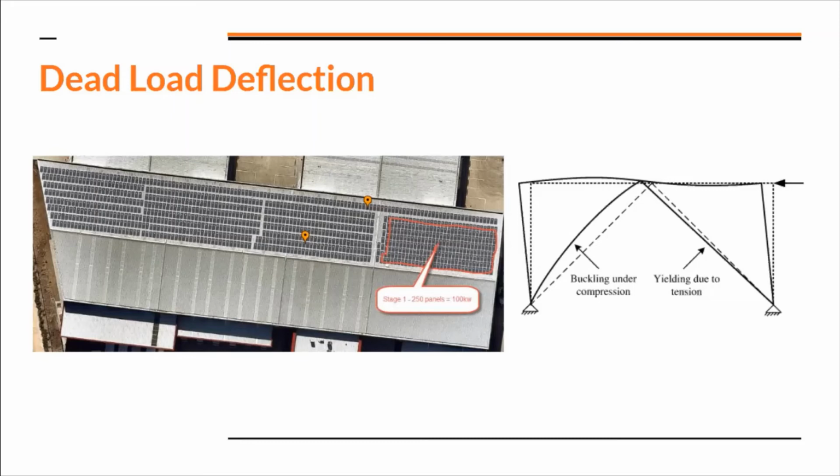the integrity of a building is effectively in its portal shape. The image I showed you before where it had 2 columns and the rafters, that is almost like a fixed and rigid system. Now, the second you want to load up one side of that, you're going to get bending in that triangle almost. And then you start losing the integrity of that triangle strength.